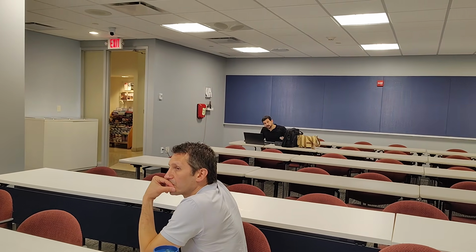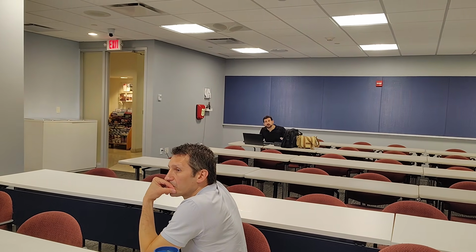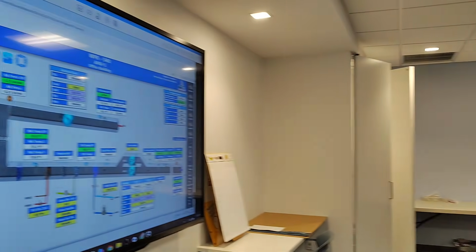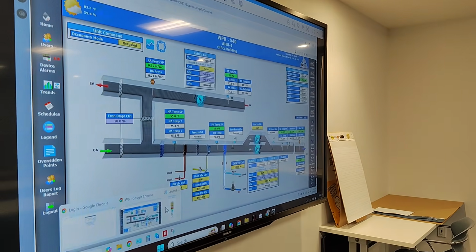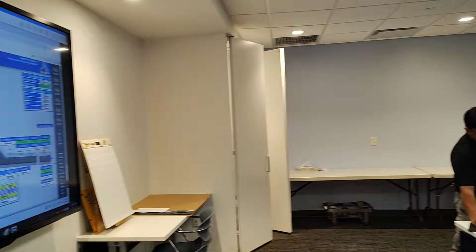Right? So if we were to take over that AHU1 system, you would then have full control over AHU1. Say there's 2 supply fans, 1 return fan, that whole system right now is still controlled by Siemens and we're just interacting with it. I would take over every point on that. I would own the valves, I would own the dampers, I would own the sensors, I would own the static pressure, I would own it all. Once I have that, I can write my own sequence, Dinesh will program it, and then you will have exactly what we decide together you want.